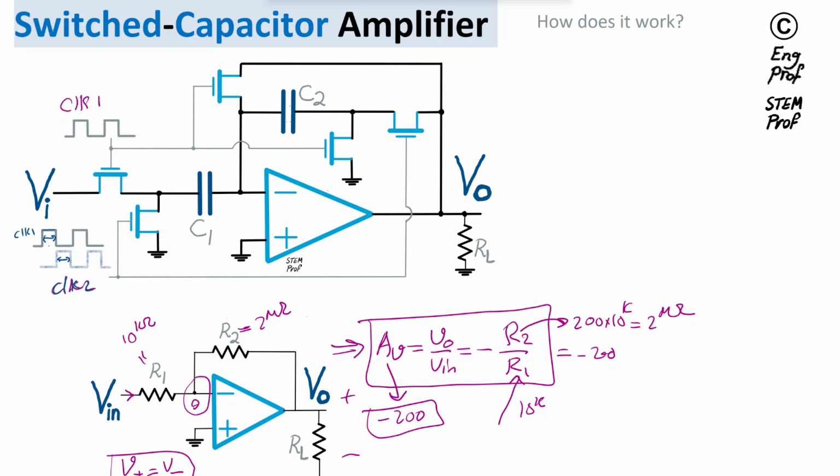So in the implementation that we have, when clock 1 is on, then this switch, which is a very small transistor, we can just make the assumption it's like an ideal switch. In practice, it's not an ideal switch. There is a non-zero resistance, or R-on, associated with it. But let's make the assumption that R-on in this circuit is negligible.